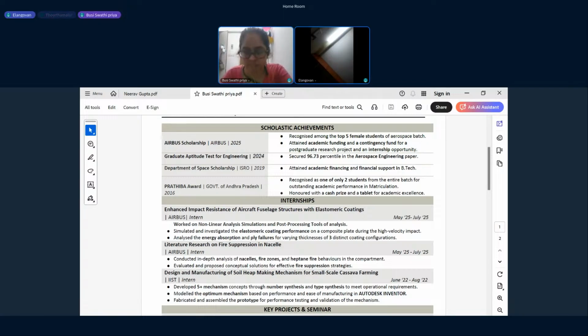Static pressure will increase, sir. Static temperature also will increase. Mach number will decrease to subsonic flow if it is a normal shock. For an oblique shock, there are some cases where the downstream Mach number can be supersonic.